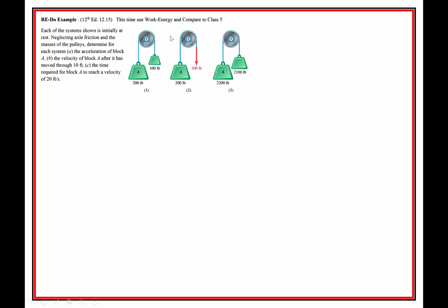Because if you look at the nature of the problem, what they essentially want you to get out of it is that a 100-pound load in this scenario does not have the same effect as a 100-pound force, because the mass of this load is going to affect the acceleration of the system, and inevitably the velocity of the system. Which we'll see here in a second.